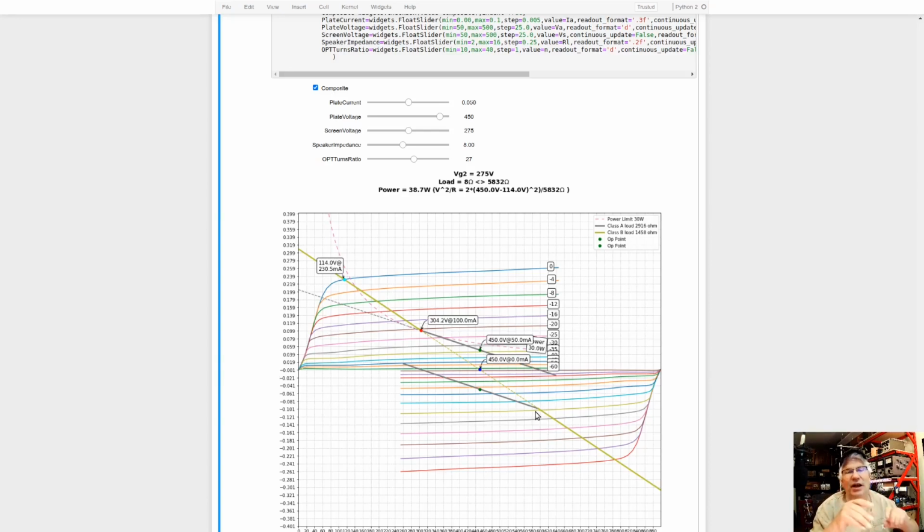I don't want to get into that, but on a guitar amplifier, you don't really care about any of that because that mismatch, all that's going to lead to is distortion, which you kind of want to introduce on a guitar amplifier. So if you're reasonably in the ballpark of the currents, you're good. Or the tube matching, it's going to be okay.